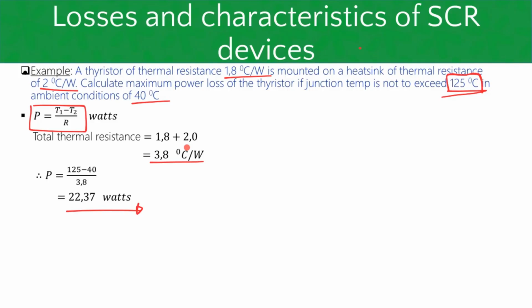Right, so another thing that we haven't looked at is limiting. I think in the previous class I did speak of the effect of high current rise. If the current rise is too high, meaning your current changes too quickly through your SCR, it can cause the SCR to not be able to dissipate the heat fast enough, and then you can go over the temperature rating of your junction.